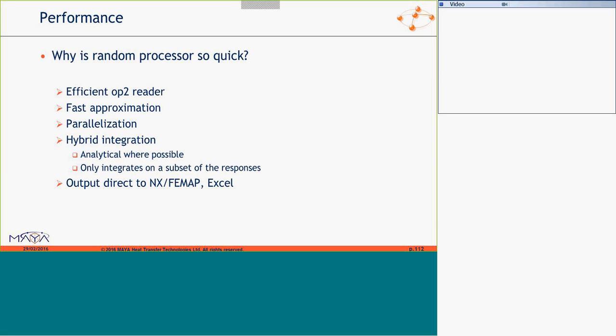Okay, I'll ask Jacques about that. I have to leave, so. Okay. So you run the analysis, your stresses, and you apply your factor of safety, and you're within 2%. You better do it the slow way. Well, with fast approximation, you don't need that. So if you toggle on exact, it's not even going to calculate the worst case von Mises. It's just going to use the fast approximation for all your von Mises stresses.